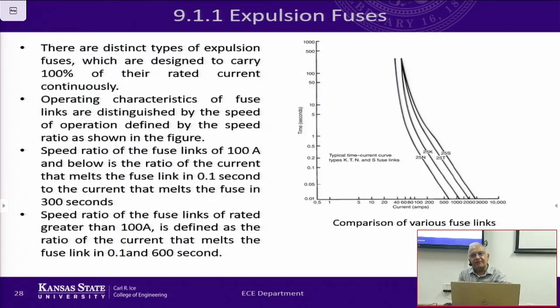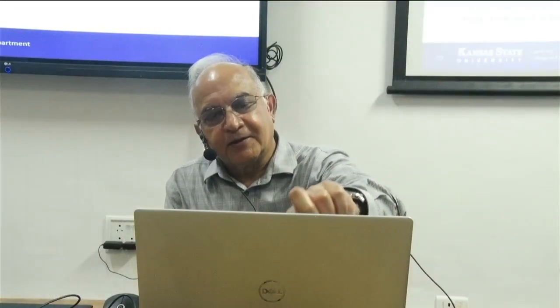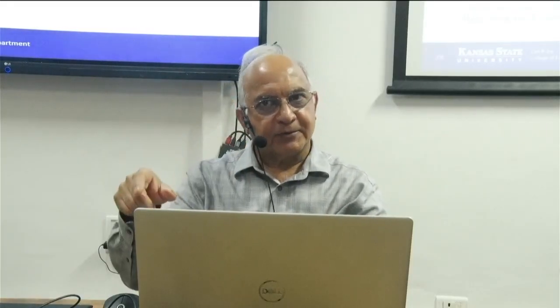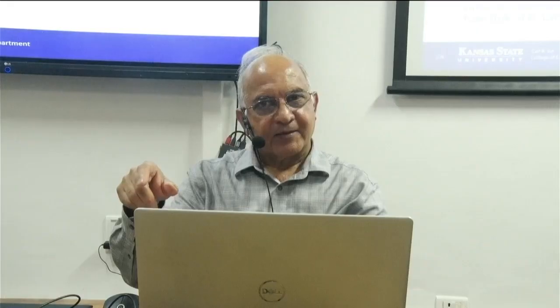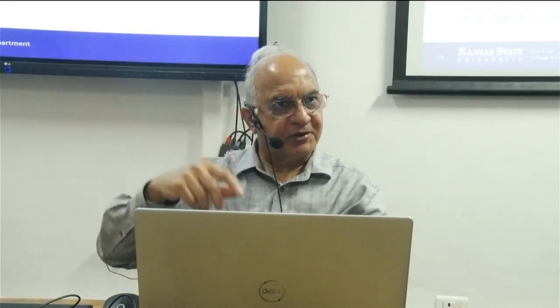Now, 65, that number essentially means that's the rating of the fuse. In general, except for the N-type, K-type, T and S, you can see that they converge at that point, which is the 50 amp. So any fuse, as a general rule, will start to melt at 2 times its rating. So if you pick a 50T, 50T will melt at 100 amps. 60T will melt at 120 amps, the minimum melt.